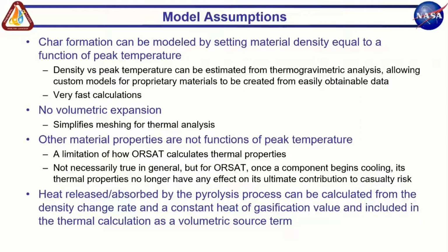This is not necessarily true, but for ORSAT, once a component begins cooling, its thermal properties no longer have any effect on its ultimate contribution to casualty risk. And so we don't care what the thermal properties are after the sample has been heated to its peak temperature. And then we can also calculate the heat released and/or absorbed by the pyrolysis process as a volumetric source term.